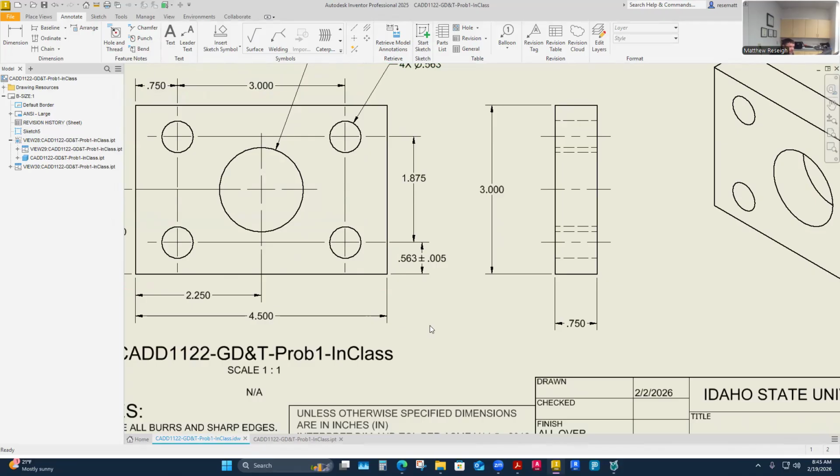Okay, that's great. So what does that look like then? What if I'm going to drill that hole in that plate? What is that going to tell me? Well, it's going to tell me that it can be off a little bit, right? If I pull my dimension from this bottom surface to there, I can be off like, really, 10 thousandths, kind of. And so what this looks like is I'm going to go back here and draw this.